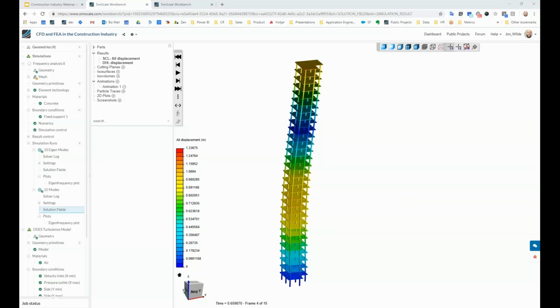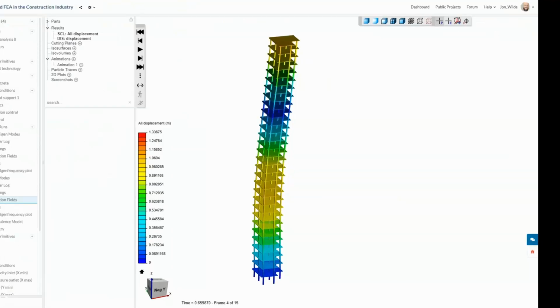And to answer your question, Ahmed, I think I did answer. You could have a set of buildings or a set of building blocks, really as complicated as you want to make it. The way the lattice Boltzmann solver works is that it can capture a lot of really complicated geometry without much fuss or hassle, and without needing any additional thought as to refining the mesh. So I suggest you simply give it a go. Okay, that's actually answered everyone's questions so far, I think.